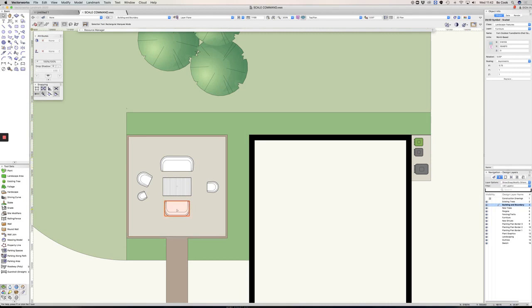Okay, so always remember that if you're wanting to change a symbol permanently and you go inside that symbol and make it bigger or smaller, it will also affect all other symbol instances on your drawing. So this is why sometimes you want to do just this factor scaling, because then you can just play around with it, make something a little bit bigger, a little bit smaller, but you haven't then affected all of the other objects on your drawing.